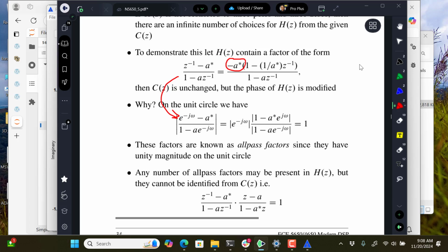When we're doing modeling, in an example problem that comes up fairly soon, this is the type of thing you end up playing with, and then those gain factors come flying out, and those show up in one of the homework problems for sure. But this is just proving that this original form is indeed all-pass in magnitude. It's just this over this, and they're conjugates of each other, so their magnitudes are equal. And I had to factor out an e to the minus j omega, but that has magnitude of 1.